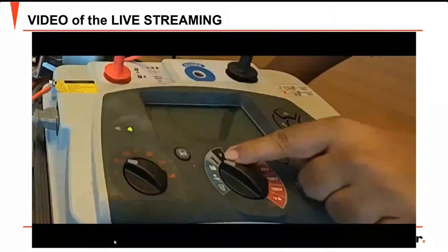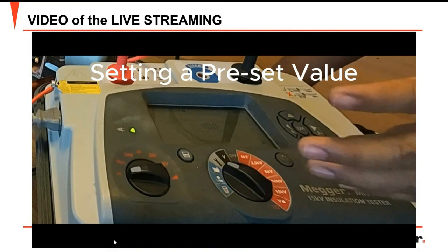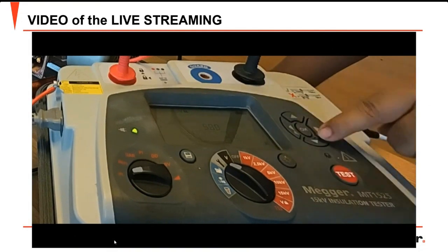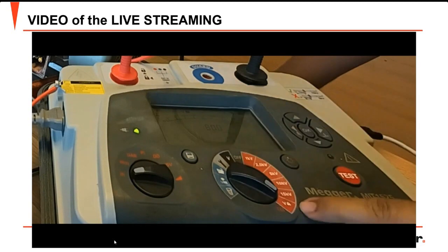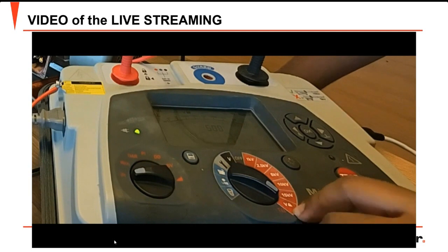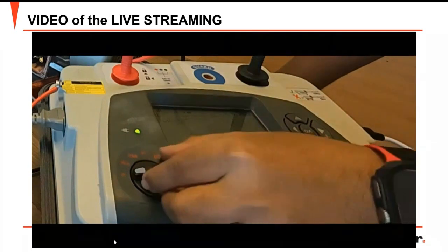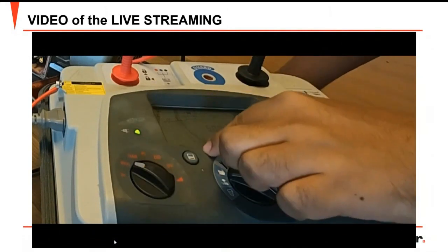As you can see, 100, and then select the IR, and then you can customize the test voltage here. So you can put 480 if you want, or I will do 500 volts, and then I click OK. So that's 500. That 500 will be seen in this voltage output here, right? You can see the voltage with the lock symbol, padlock symbol.